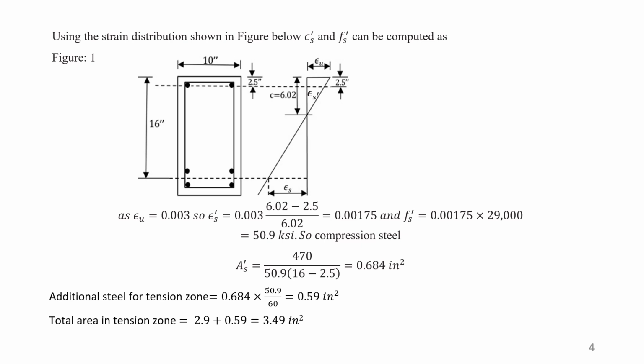That is shown here with arrows. And we will provide the steel at the compression zone at a depth of 2.5 inch from the top surface, and that 2.5 inch is shown. Along the dotted line below the 2.5 inch mark, the steel will be placed there. We have not shown the steel in the strain diagram, but we have shown it in the left hand side cross section.